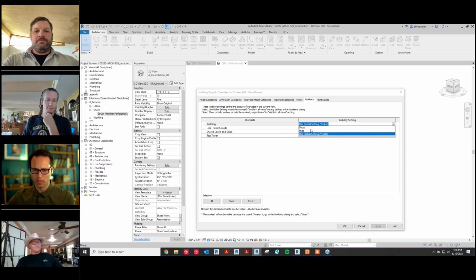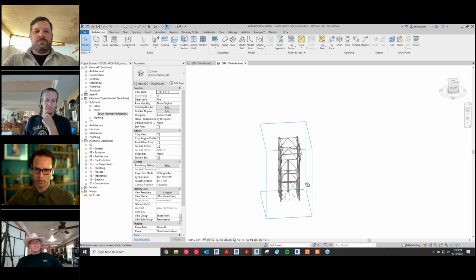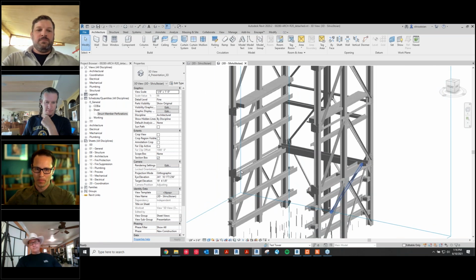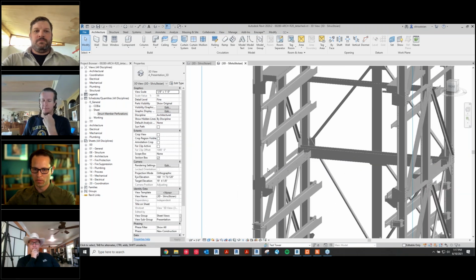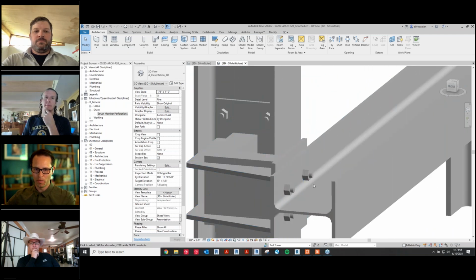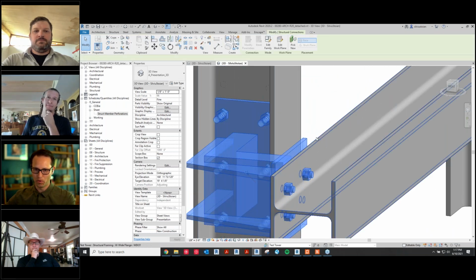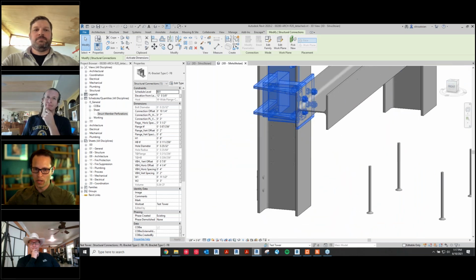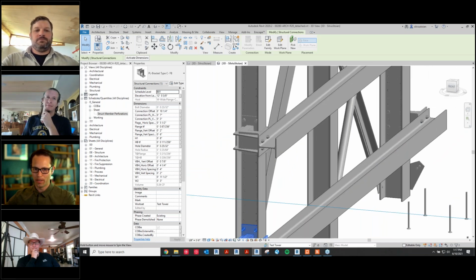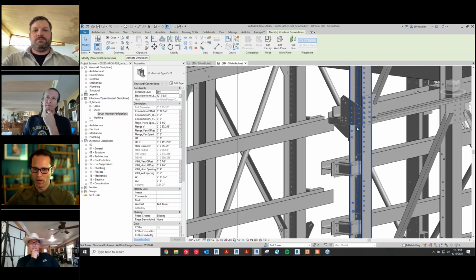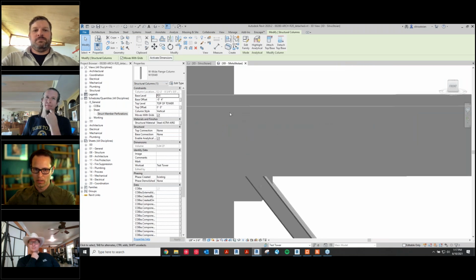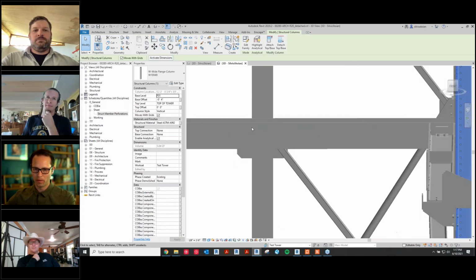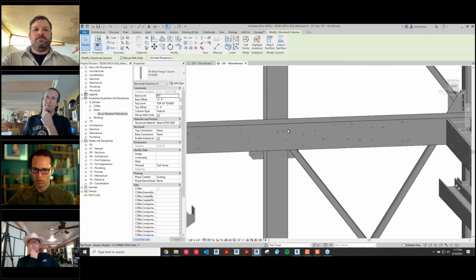So I'm going to turn off the building here and just show what's underneath it. The structure, as Kelly mentioned, is steel. No documentation at all was available. So you can see that here we modeled all the connections with all the nuts and bolts, as well as any penetrations that we found on the surface of these elements, because the client wanted to calculate the actual surface area of the flanges and the webs of all these members.